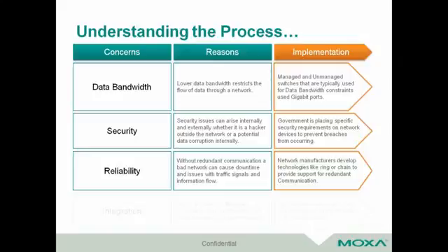Now, what I've seen is that there are some infrastructure requirements. Serial signal controllers are still widely used, and some of those still use serial communications. In those cases, you can get a device server that can help you get that communication over to Ethernet if you're already migrating. But there are some serial signal controllers that also use Ethernet, interestingly enough. So it helps you still utilize and gather that data with newer technology.